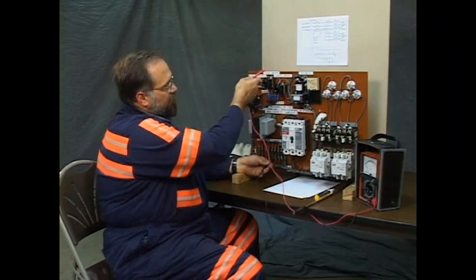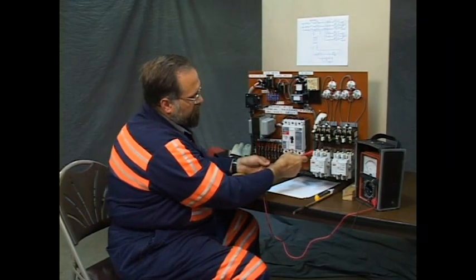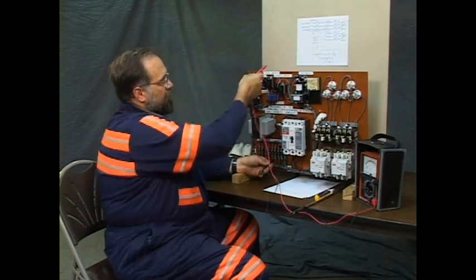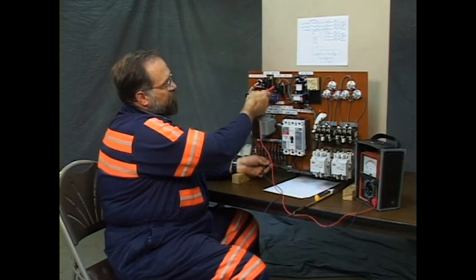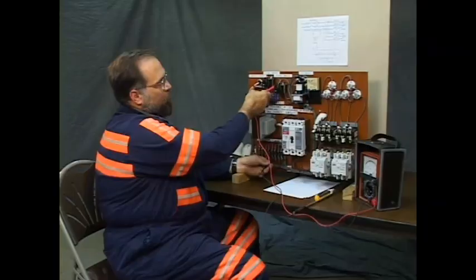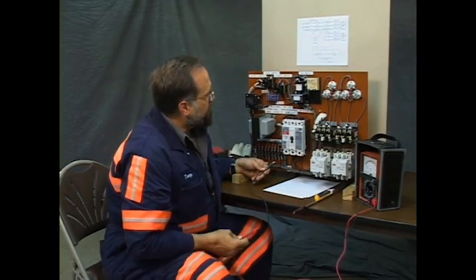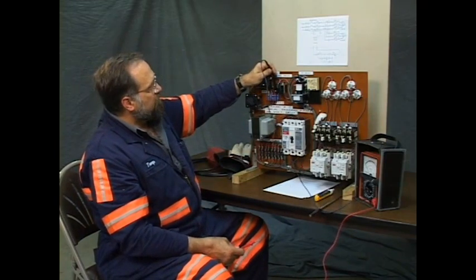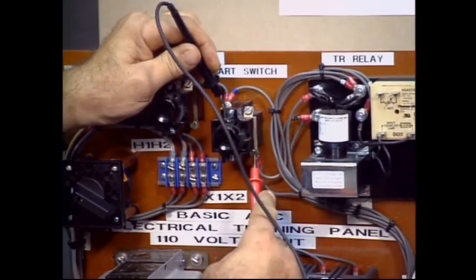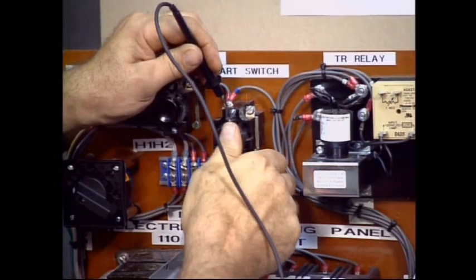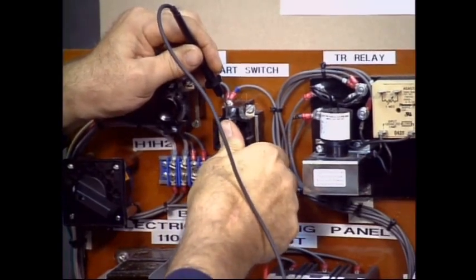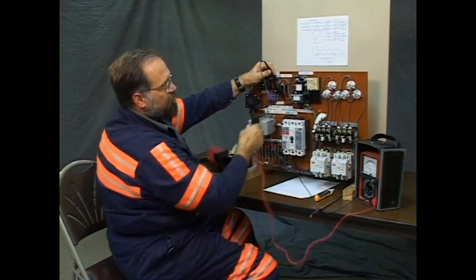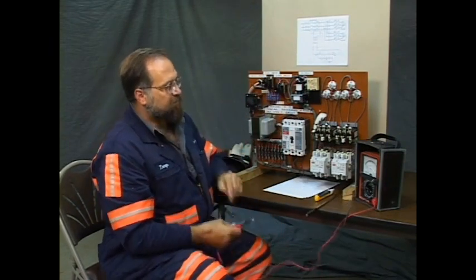From there, the next point from the stop switch would be the A auxiliary. Again, perfect circuit. And to the start switch. No problem there. Well then, I'm going to read the start switch. It's supposed to be normally open, and it shows normally open. I'm going to press it with my thumb to make the circuit. Looky here. No problem. No resistance. I'm reading through the start switch, so I know it's not a bad switch keeping it from running.